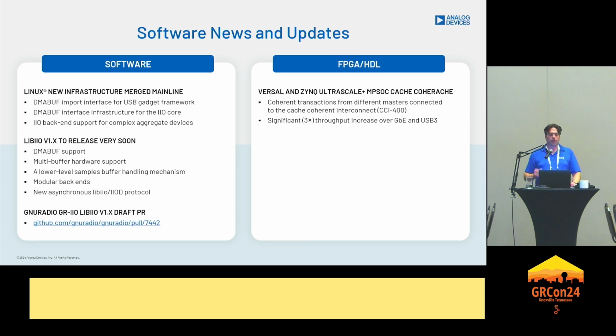It was like going through each page, 4 kilobytes at a time, executing code, and waiting until the flush succeeded or the invalidate. By just having this done automatically by the hardware, we see a significant 3x boost. Where we did 50 megasamples before, it was all of a sudden 150 megasamples over USB.